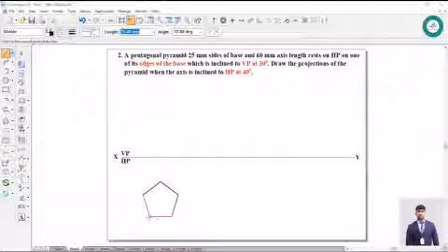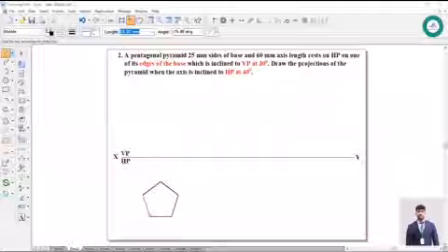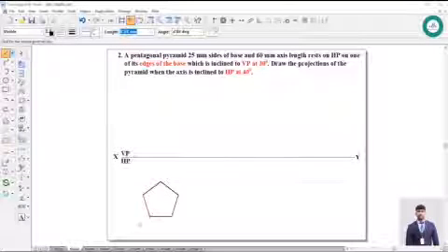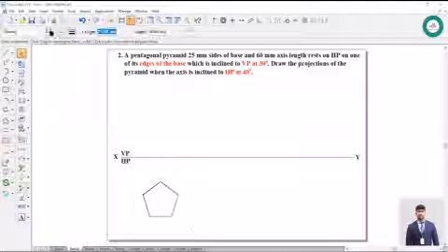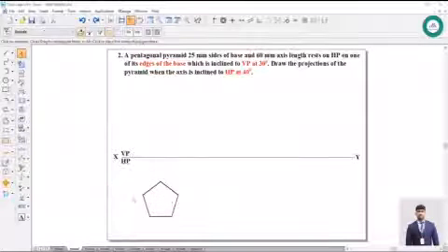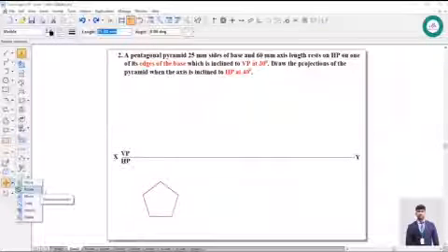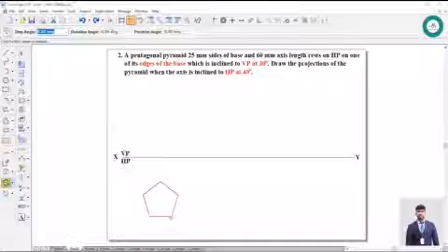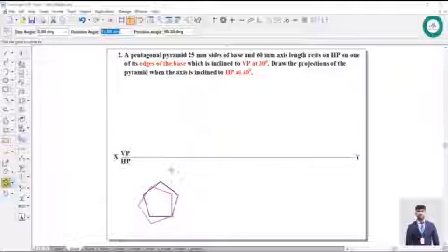This to an end point, or else you can give the value here 25 and minus 72. You can make a note. So click this. After drawing this, select this particular, go to move command, place this nearer, and come to this rotate command. Rotate this, ensure we want an edge to the right side. Select this and this and make this particular straight or else vertical.